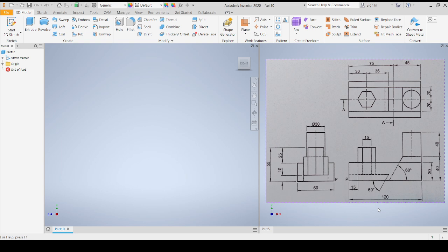The one that suits me and that I'm comfortable with, I'm going to start off with, is the right view. Using the right view and my guide as the top view, because in the top view you've got the hexagon, and then you project down, you can see the level of extrusion, right? And from there onwards, as I keep on designing the right view with reference to the top view, you would end up getting the front view, right?